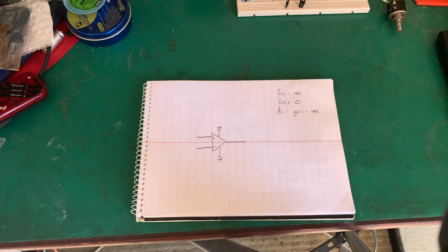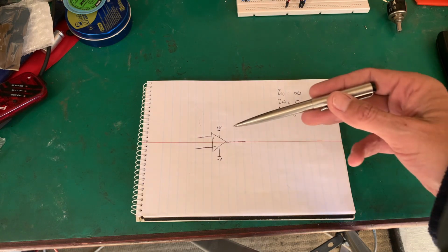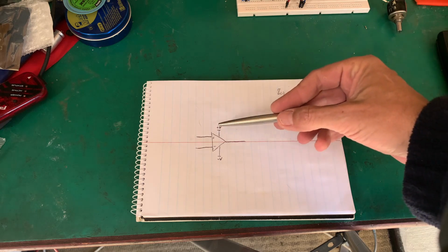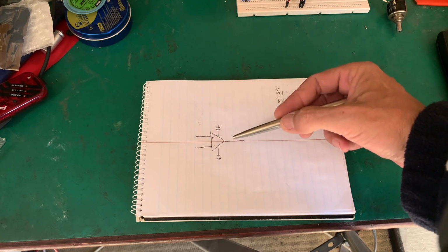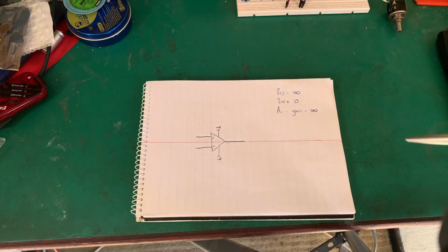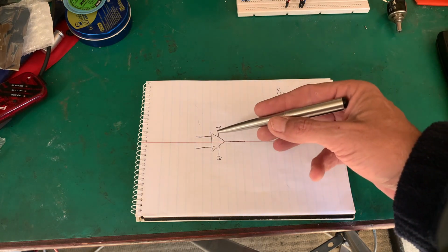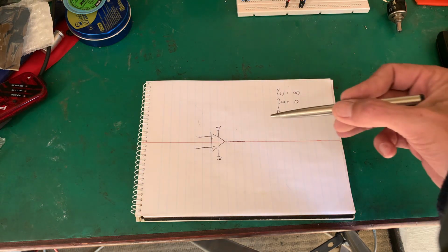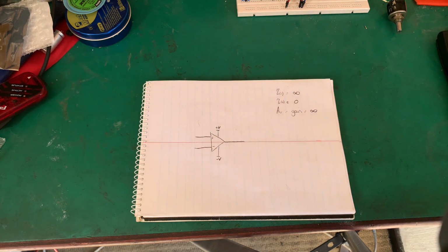Right, so here we are on the bench and what we can see is our symbol for the humble op amp. You'll notice it's got a little plus sign there and a negative sign. And we have a power supply, two inputs and an output. The plus sign is a little bit misleading. It's not plus. What they call that is the non-inverting input. Now, that sounds like a mouthful, but it's really very simple. The negative sign denotes the inverting input.